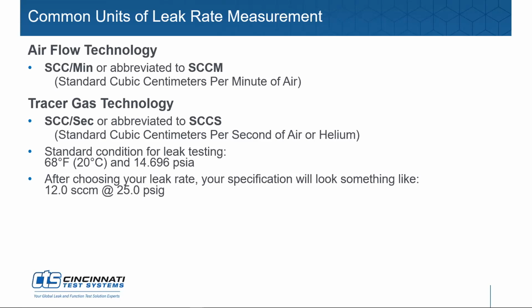And the reason that you standardize or normalize your flow when you're calibrating a system like this is so that you can correlate your testing at atmospheric pressure after you've calibrated. And atmospheric pressure differences are different here in Cincinnati than they are throughout the places in the Carolinas and throughout the world. So Cincinnati versus Mexico City versus Denver, Colorado. You've now correlated all your calibration back to one condition, that standard atmospheric pressure at sea level at a certain temperature. So you can correlate all your testing results worldwide that way.